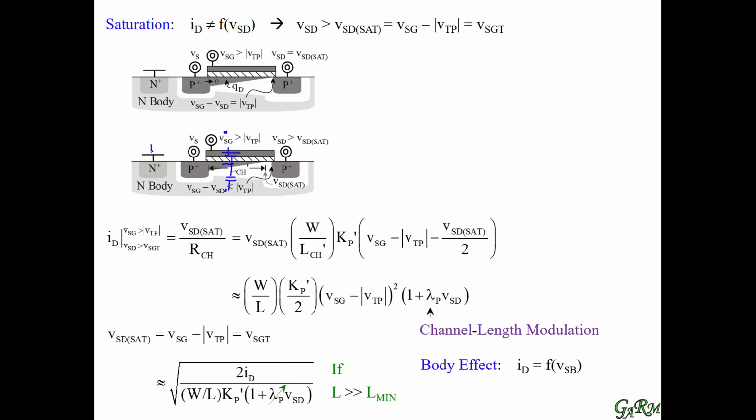So when we apply positive voltage to the body, we induce a positive voltage at the channel, and that will repel holes back. Repelling holes back is like increasing resistance, but in another way of modeling that, it is like increasing threshold. So this is the expression that we use to model that.